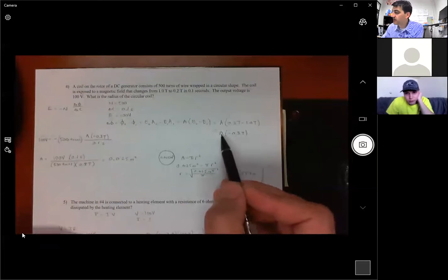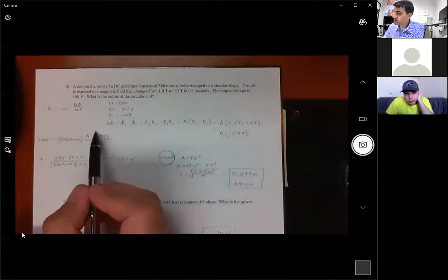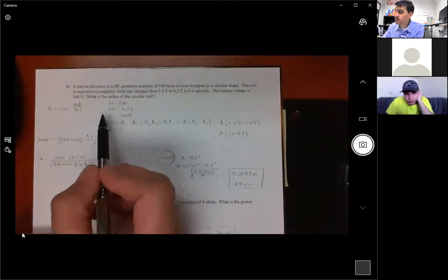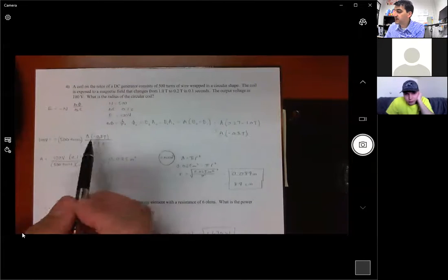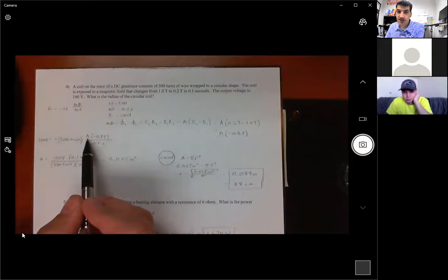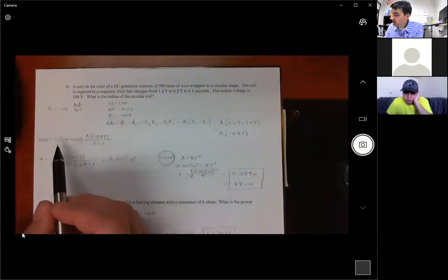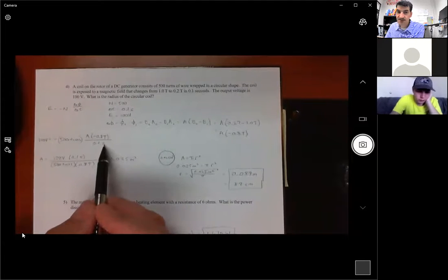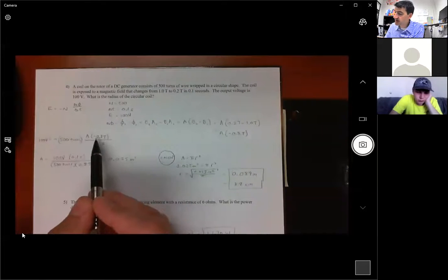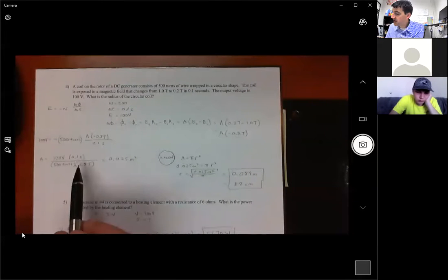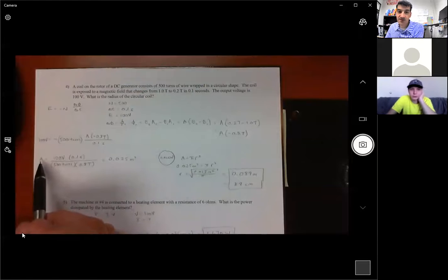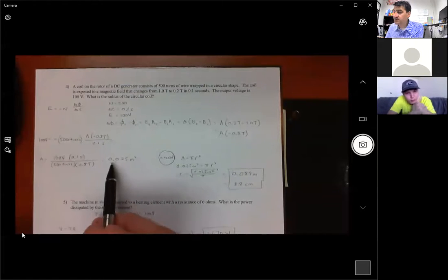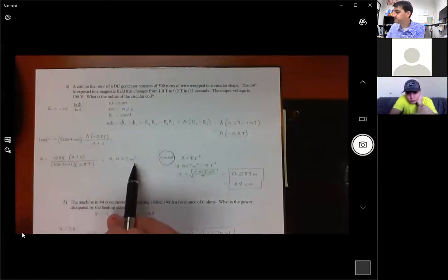Either way, you plug that in to your value for the change of magnetic flux, and you can plug all these other known values in as well. And now the only unknown in this equation is the area of the armature. So you can solve for that. The negative signs are going to cancel out here and here. And you're going to multiply both sides times 0.1 seconds and divide both sides by 500 turns and 0.8 Tesla. And your answer then, remember your area is always going to be in meters squared, so your answer is 0.025 meters squared.